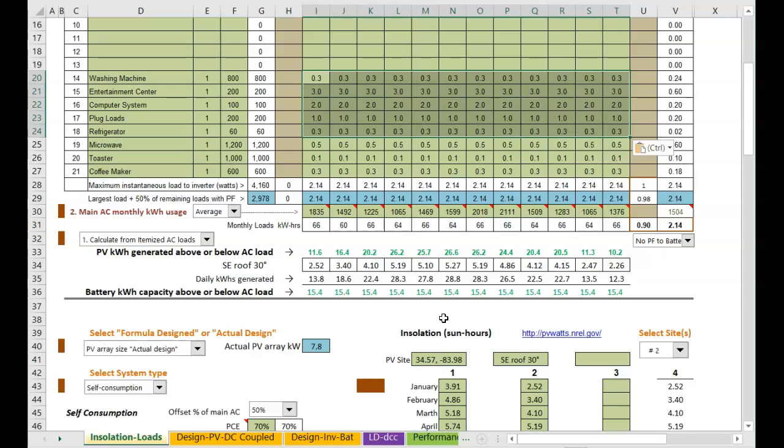Typically we start out by identifying all of our loads when we're going for the battery system. But we don't do that as much today. We often build an interactive PV system and later add batteries. And when we do that, we have to explore in reverse what we can actually set up on it.